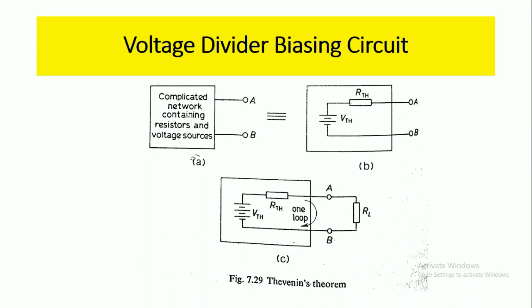The Thevenin's equivalent voltage source VThevenin is the open circuit voltage across the terminals A and B. The Thevenin's resistance RTh is the resistance from A to B when all the sources in the network are reduced to 0, that is, we make them short circuits, so that we get the RThevenin value of the circuit. After Thevenizing the circuit at the A and B terminals, we may connect any resistor across A and B and calculate the current flowing through it.